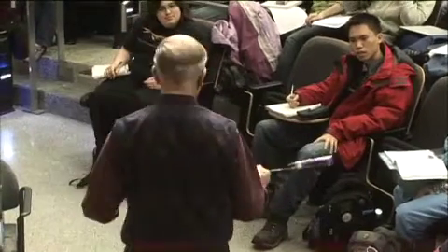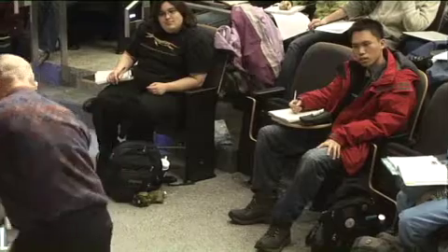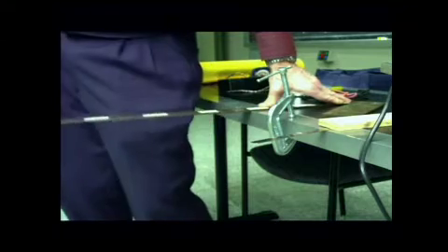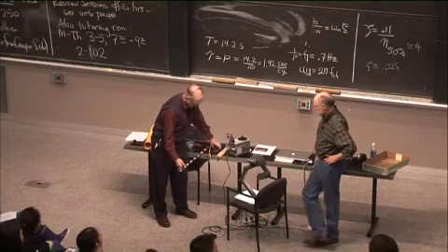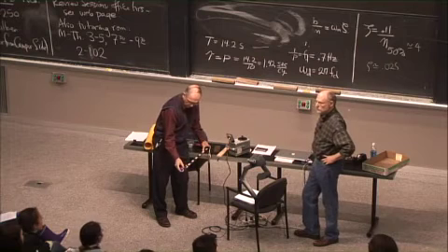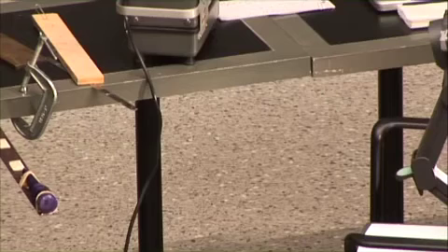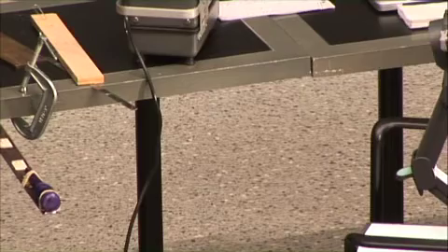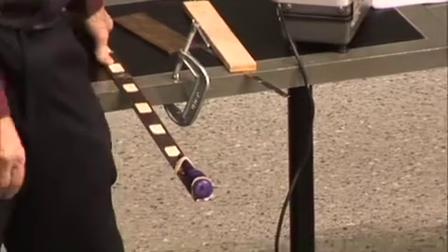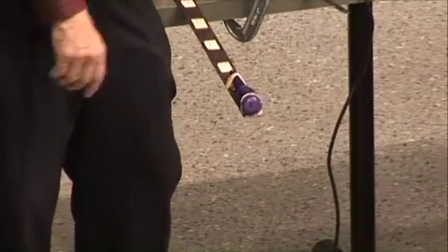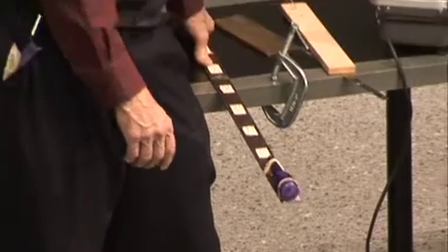Now, a beam will vibrate, and it has a natural frequency, that's in this case, like you can see there. And if I turn on this squiggle pen, it's going pretty fast, actually, 30 hertz or so. Much, much faster than this beam's natural frequency. So you don't see much vibration. But the beam's natural frequency is a function of its length. And in fact, it goes roughly like 1 over length squared.